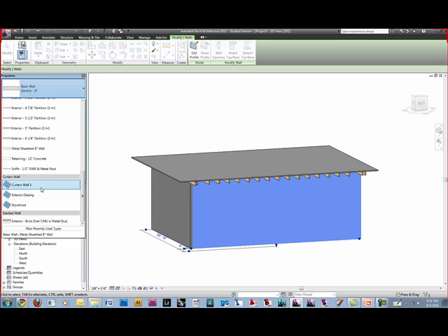So we're going to say curtain wall 1 versus exterior glazing, which actually comes with divisions, just no mullions. And storefront comes with divisions and mullions. So if you had a set pattern you wanted to follow, you can start with a storefront and change spacing. Or if you had a grid you wanted to follow and then place your own custom mullions, you could go with this option.